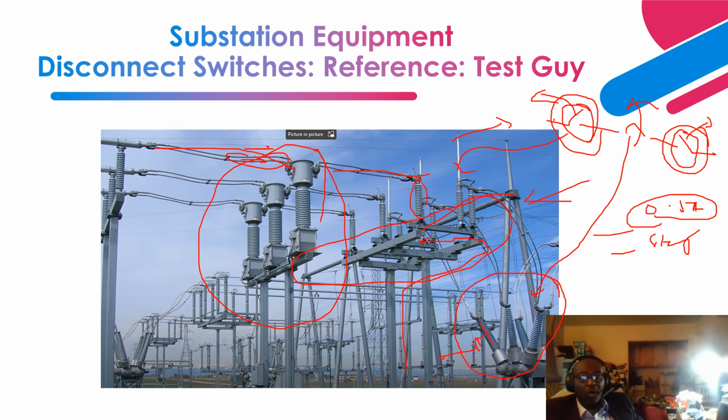This one is support insulators. Support insulators are basically to protect and provide a ground plane to the live conductor. This conductor is live, right? So basically, based on the voltage level, the support insulators are designed and the number of sheds is selected based on that.